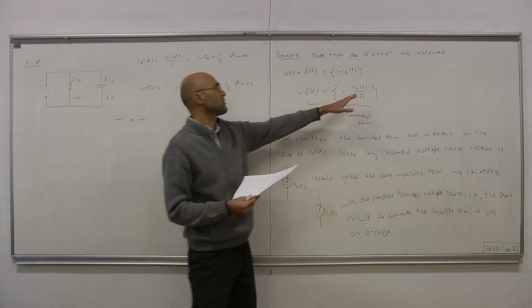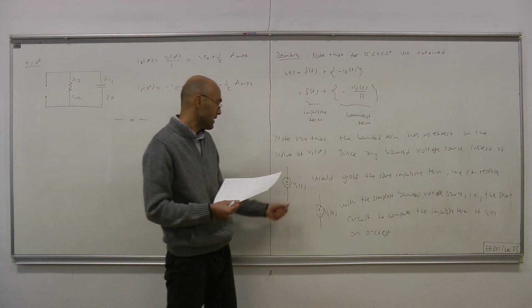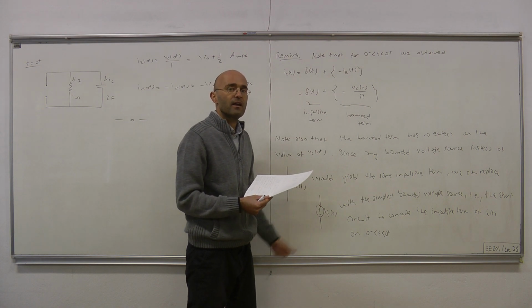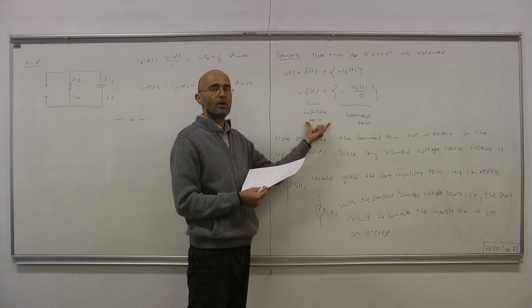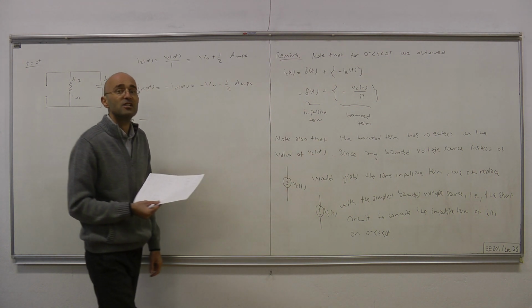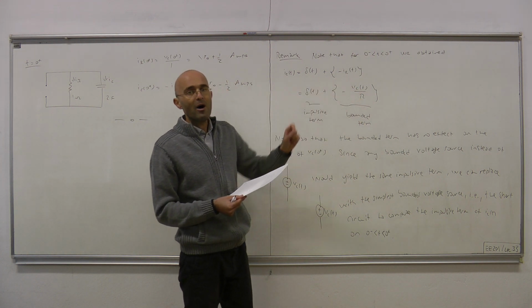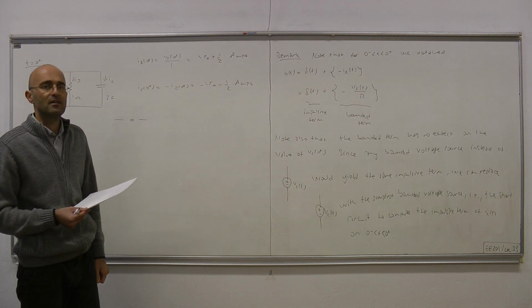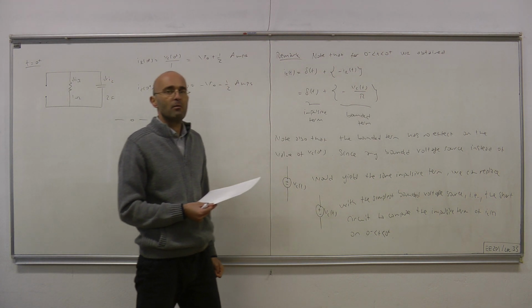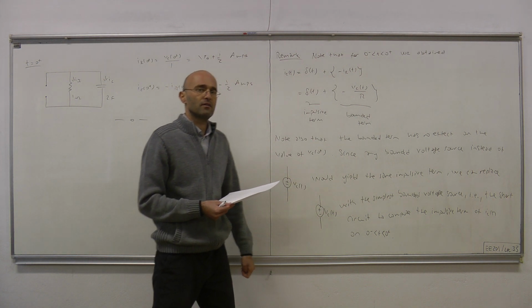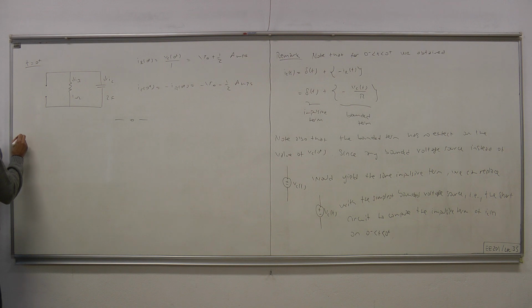You replace that voltage source with any other bounded voltage source, and it may not give v_C, whatever the capacitor voltage is, still you will get the same impulsive term. So if that's the case, why not use the simplest possible bounded voltage source for our analysis? And the simplest possible bounded voltage source is a short circuit. So with that suggestion, let's revisit our example.